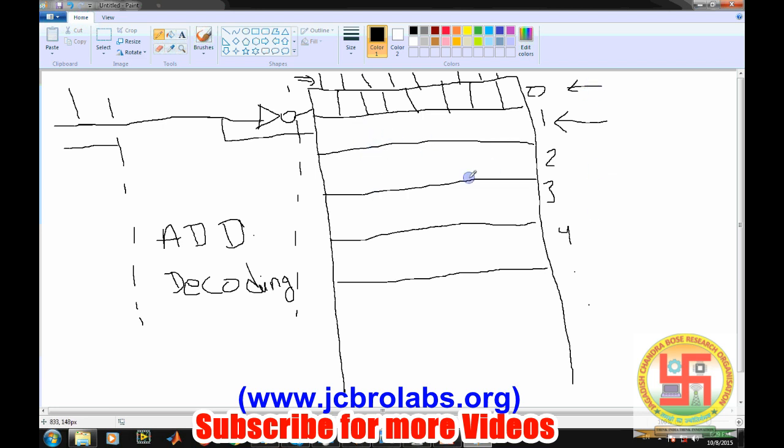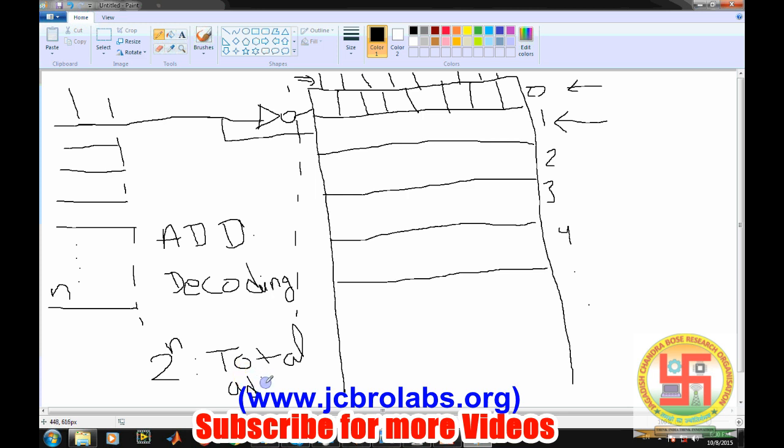Address means the memory locations which we are targeting, because ultimately in RAM or ROM, these are the memory locations. Now if we have 3 wires, we can have 8 memory locations. With 4 wires, we can have 16. With 5 wires, we can have 2 to the power 5, 32 different addresses, and so on. So suppose we have n wires, then we can have 2 to the power n different addresses. This is the total number of addresses which we can access by n wires.